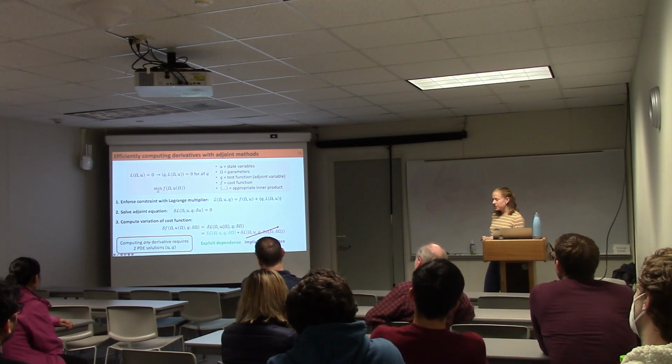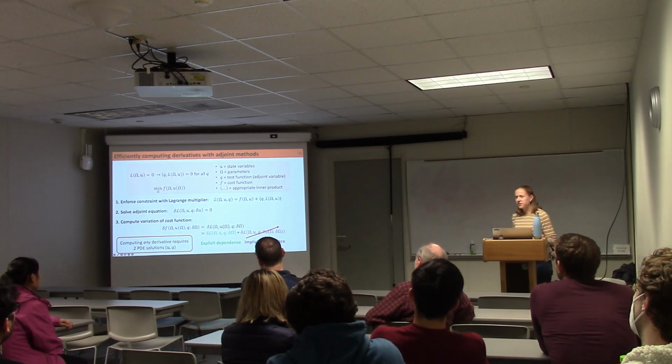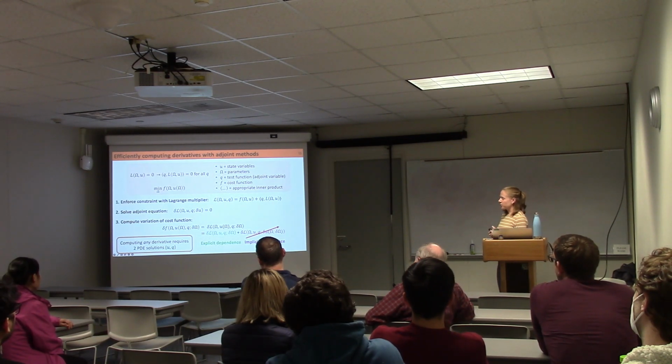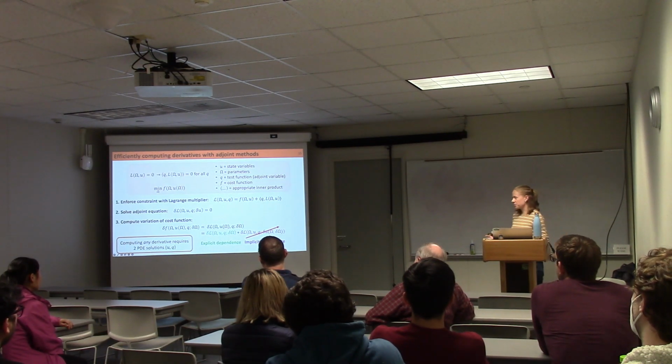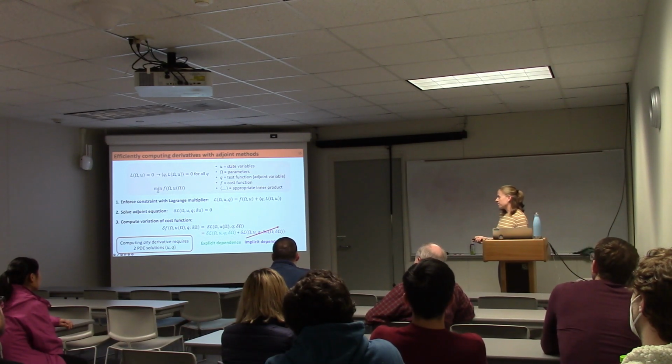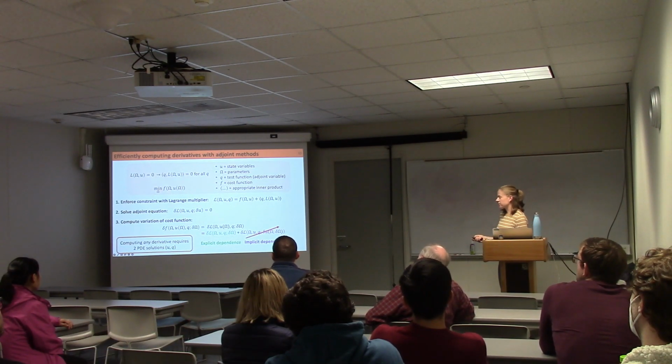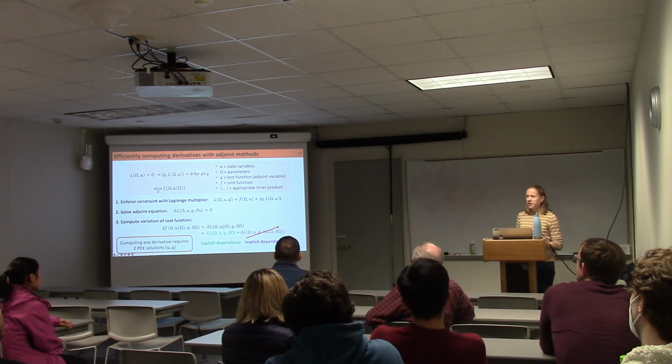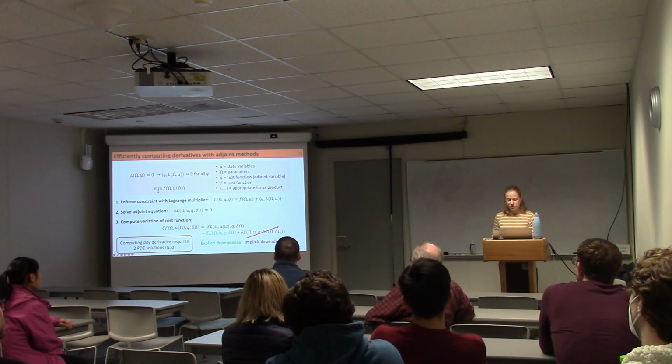And with those two PDE solutions, we can get all the sensitivity information with respect to any perturbation of our system. While typically you would have to perturb with respect to every parameter that describes your boundary or your coils, which could be hundreds of parameters, you can instead get all the sensitivity just through these two PDE solves. That's really the win that you get out of the adjoint method. And you get a lot of bang for your buck if you're doing stellarator optimization, because we have this high dimensional space.